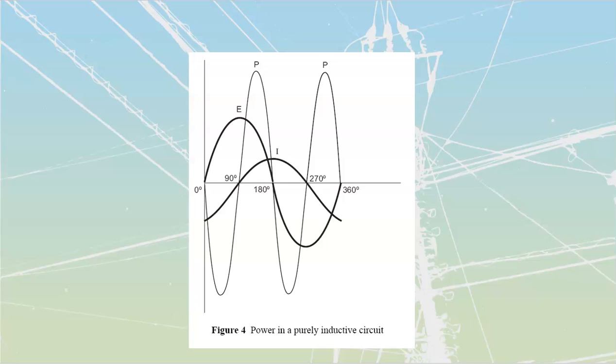This power waveform that we're seeing is going to be power that is developed from my inductor. And it's really funky, because when I take a look at it, well, first of all, let's go with the formula. Watts is equal to E times I, my current times my voltage. If I take a look at it, I've got a positive E and a negative I, so positive times a negative means that I'm going to have a negative value of power.